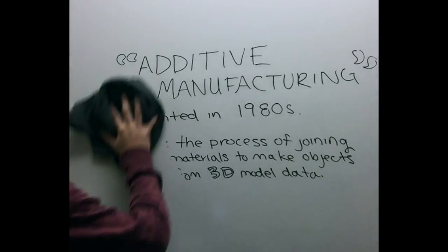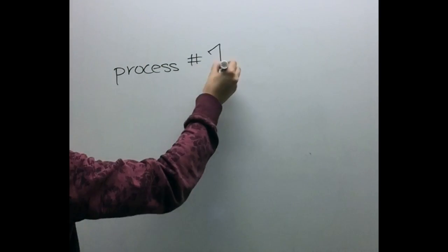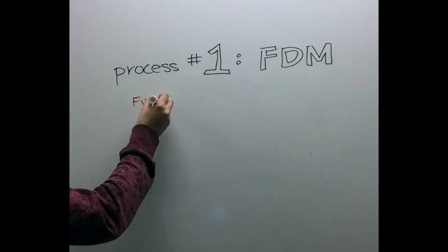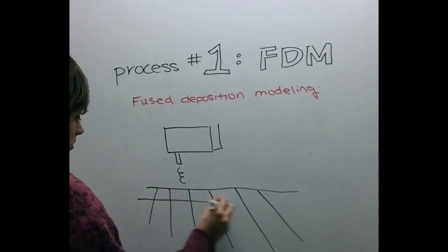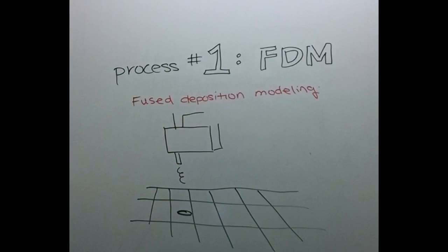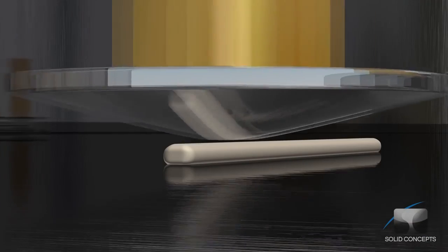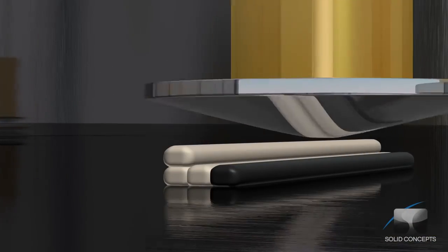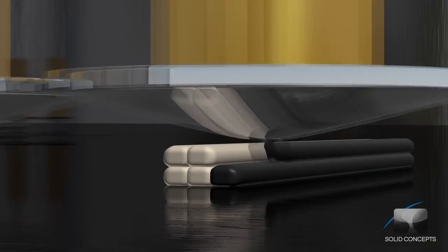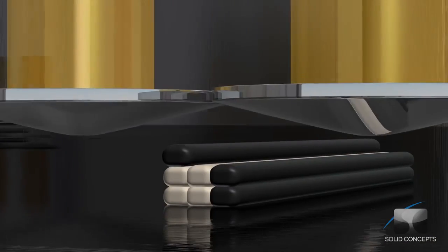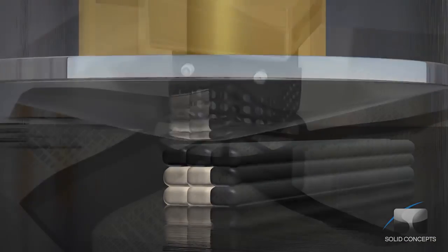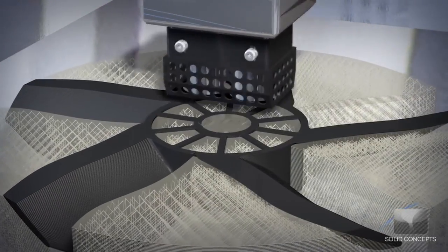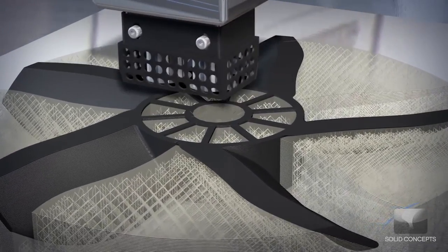However, modern 3D printing technology has expanded to a plethora of methods used ultimately to print something in 3 planes of motion, put simply. The first of 3 common forms of 3D printing highlighted in this video is called fused deposition modeling, or FDM for short. Machines designed to carry out such a process vary in size, from home desk printers to commercialized output. This is personally the method of 3D printing that comes to mind when someone mentions the topic. The arm of the machine moves in all 3 axes of direction, X, Y, and Z, building a layer in the XY plane one at a time. The material is melted on application.